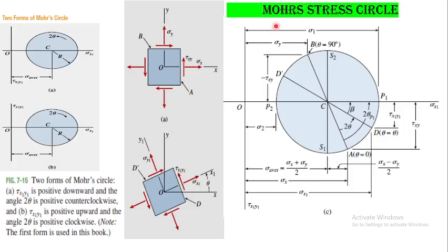Before that, remember, the Mohr stress circle is a very powerful analytical tool for engineers to calculate the normal stresses and shear stresses and their orientation within the material. You can calculate them very easily. Apart from that, you could also calculate the maximum principal stresses on the Mohr stress circle, which will be helpful in designing materials, as they respond to the yield of the material. So you have to stay below these values of sigma 1.